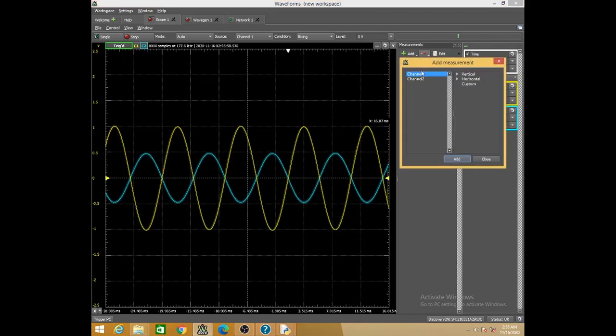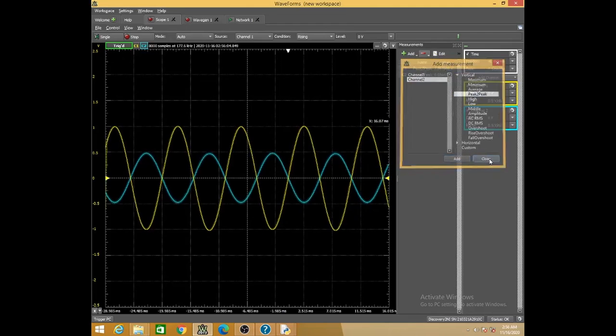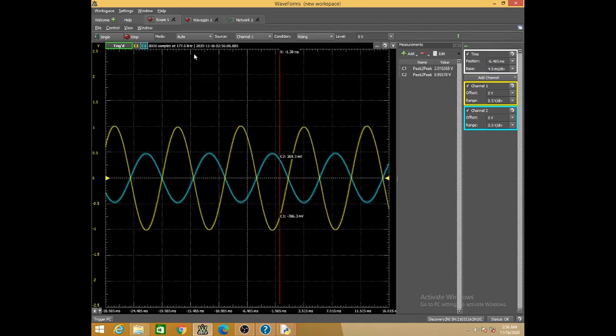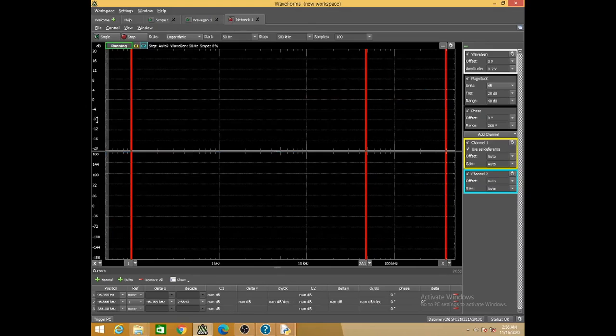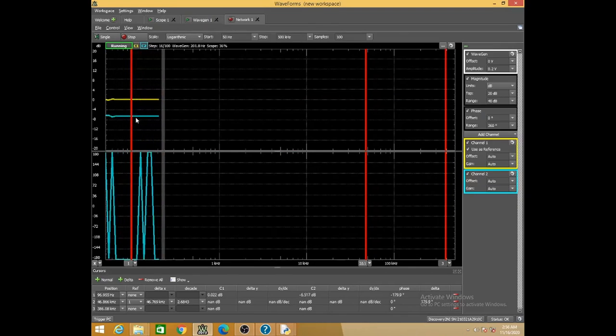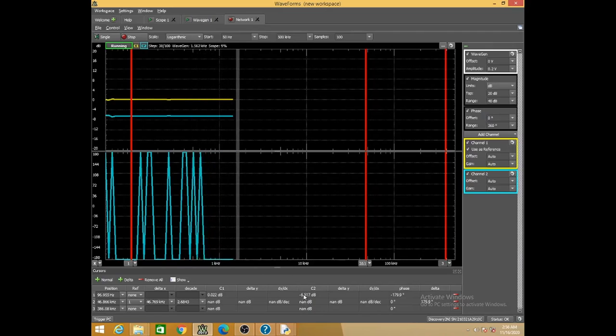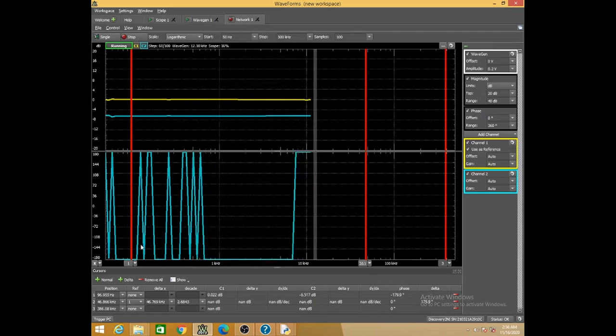Now this is a different combination of R1 and RF, so that we have a gain less than 1. That's why you can see the output is lesser in amplitude compared to input. Sorry, output is lesser than input. And if you can see the Bode plot is less than 0 dB. Can you see now it is negative magnitude? You can see now it is minus 6.51 dB.